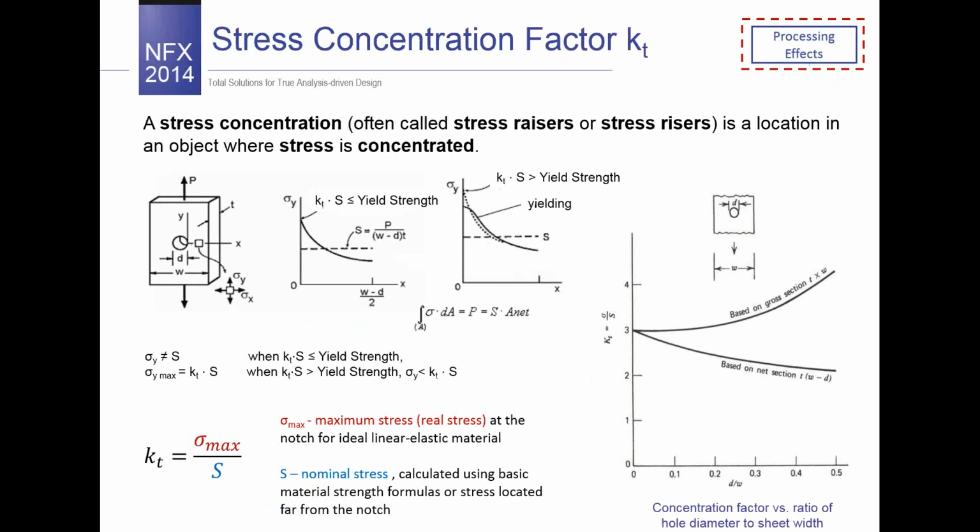Usually mechanical parts and structural elements have some features that can cause sudden changes in the geometry. Under loads, some changes in the geometry increase the local stress fields of the parts significantly, and they usually represent locations from which parts start to fail. This localization of high stresses is called stress concentration.